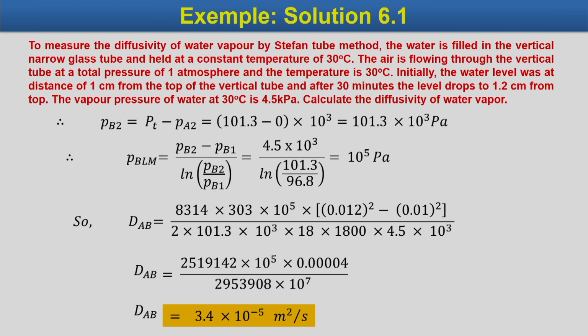In this case we should note that there should be a gap between the horizontal tube and the liquid filled in the vertical tube. Otherwise, if the vertical tube is completely filled, then there will be turbulence at the top surface, and we cannot consider the case as a diffusion of component A through non-diffusing B.